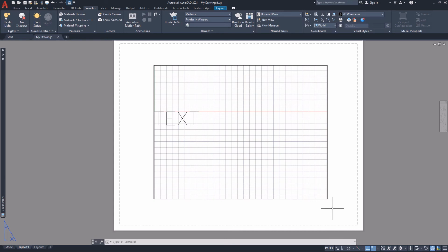At the bottom of our display and at the left end of the drawing aids toolbar, we see the word paper. We can interpret this visual cue to mean that the viewport window is not open. Therefore, we are unable to draw, create, or modify objects in model space through the viewport window. Any object that we currently draw or create will be physically, virtually drawn on the paper itself. The often used term for this is working or drawing in paper space on the paper.